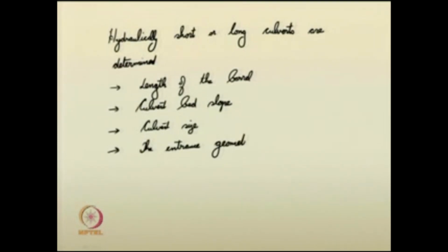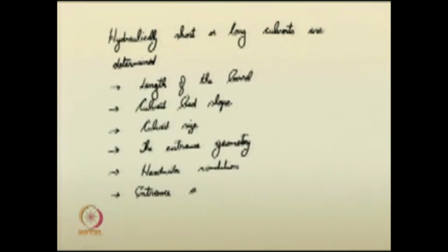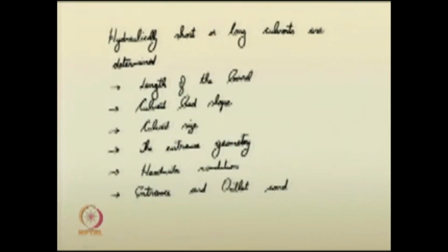You have seen how you can have circular, rectangular, square shapes and various other shapes. Then headwater conditions, also the entrance and outlet conditions, play a significant role in whether the flow in a culvert is hydraulically short or hydraulically long. These are some of the conditions, so please note them.